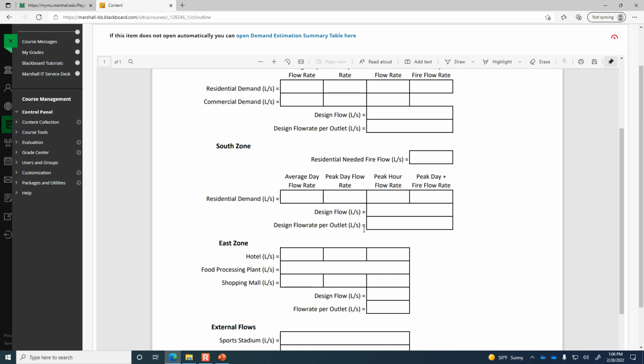So a conservative assumption. Here, I'll tell you what a non-conservative assumption would be. The factory is open 24 hours a day, 7 days a week, and so they're using that 40 million gallons over a continuous time frame. That would be non-conservative because Q is volume per time. If I assume that the factory is always open, that's a lot of time for that quantity of water to be used. But it's possible that there's factories where they're only open 40 hours a week, right?